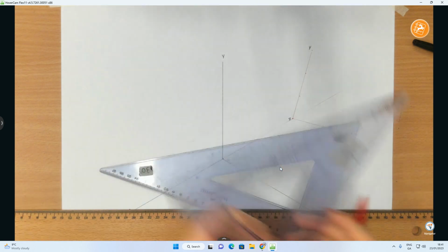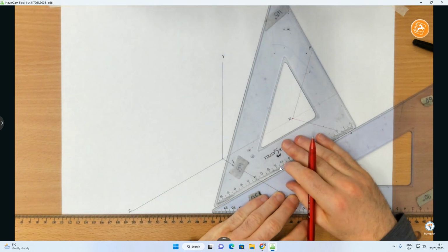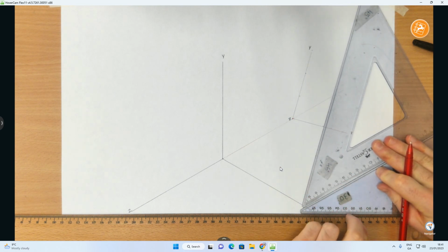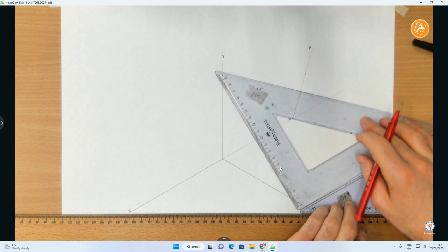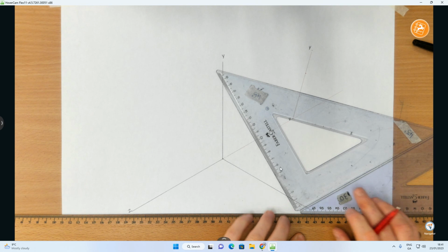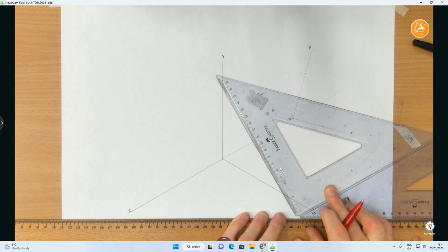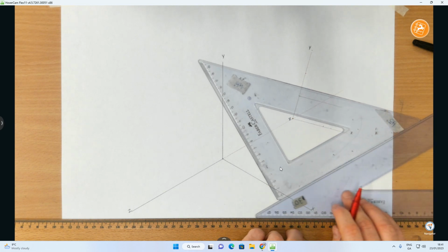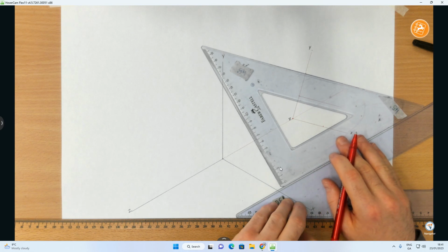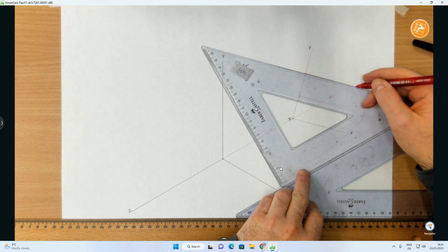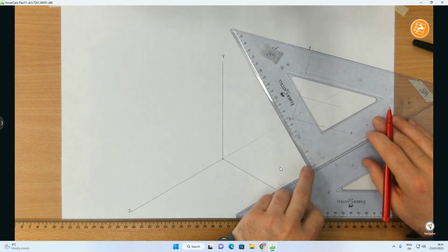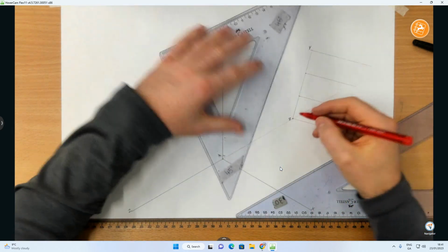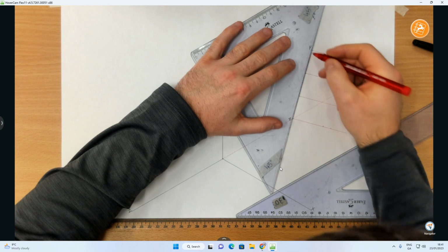Now using my set squares, once again, like this, and I just slide them across to get the vertical line. I don't actually need a vertical line on that one, so I actually just need these lines going like this. Slide them down a little bit, so just remember set squares like this will get you 15 degrees. I'm just moving my t-square down, so I'm going to do a horizontal line there. And look, you can see kind of how I have it set up like this. I can slide it along now. So here's the next height, that's the height of 60. And finally, 70, or sorry, 90 I should say. And from that line there, just extend this one a little bit further, just make sure I'm 100% accurate.